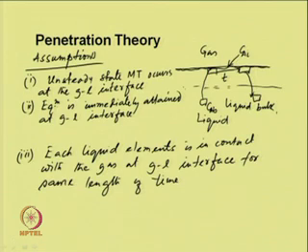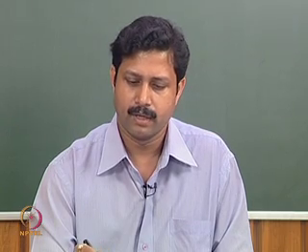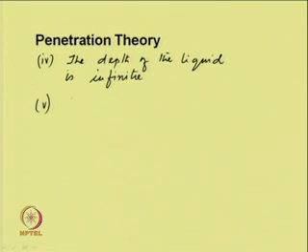This means the concentration at the interface is CAI, and immediately beyond that it remains at the bulk concentration CAB. On the other side of the element it also remains at bulk concentration, and this is possible when the contact time between gas and liquid is very short, so the interfacial concentration does not reach the bulk concentration, and immediately after that it remains at bulk concentration.